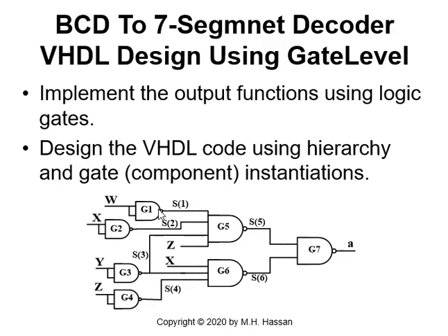We needed inverters for W, X, Y, and Z, and we have 2-input NAND gates used as inverters. And we have product terms that we can generate here. We need a 4-input NAND gate, a 3-input NAND gate, and 2-input NAND gates.